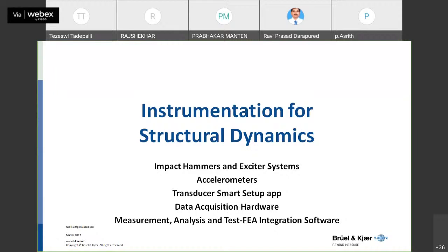However, the fundamentals of modal analysis, whether you are talking of experimental modal analysis or modal analysis, deflection shapes, fundamentals of instrumentation have not really changed over the years. Yes, you'll find that some of the instruments have developed. So accelerometers from charge have become ICP, have become wireless. But the concept of modal analysis, wherein what you are doing is measuring the output and response, seeing the damping, seeing the mode shapes, all that has not changed.